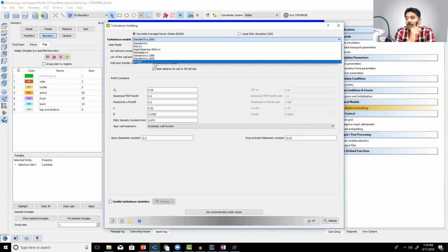So if you're using that small of a computational mesh, your total cell count will be huge. For external flow simulations, if your total cell count is less than 30 or 40 million, then the results are completely wrong. If you have 40 million cells, there is no way for you to run that on a desktop computer. So that is why, Deepak and others, I mentioned that your simulation strategies are incorrect. I hope that makes sense now.